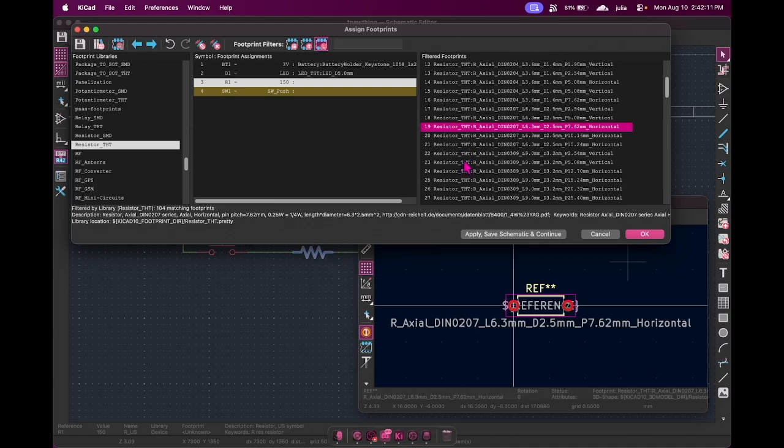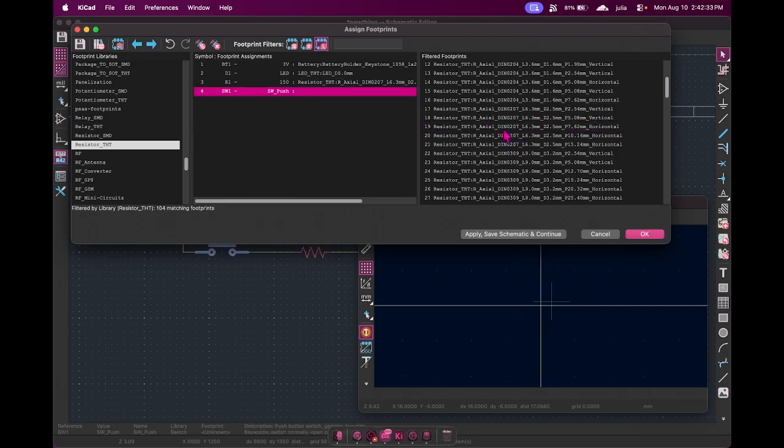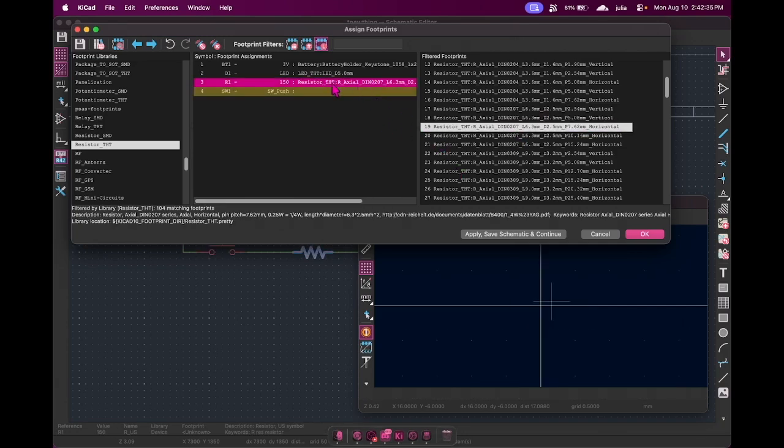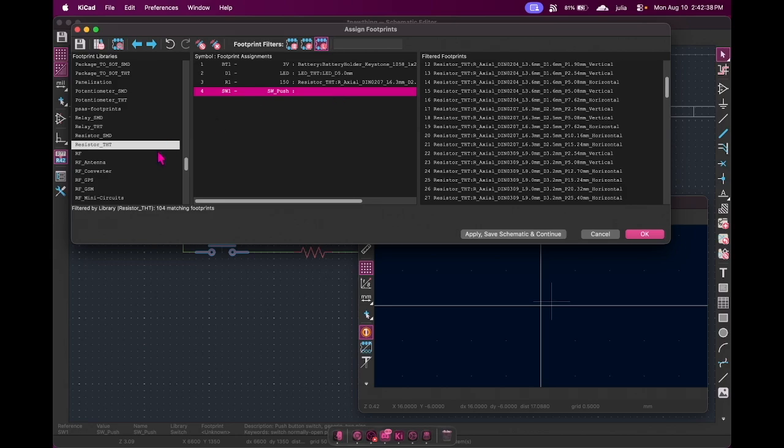When you go into the PCB layout, you can see your schematic, you can see your layout in 3D and see what the components actually look like. Then you can see, okay, this is too big, I don't like how this is shaped, I'm gonna go back and select another footprint. I'll show you guys how to switch between the 3D editor and the footprint in a second. But double click number 19 for resistor, and then lastly we have our switch, which is a button.